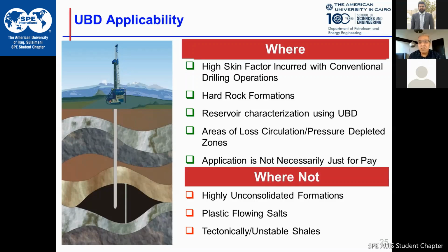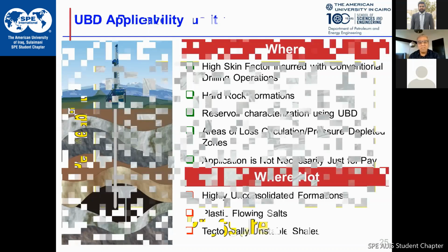Now, the other issue, if the clay content in shale is so high, let's say 40%, 50%, you have to take care of your base fluid, because if we use water, clay does swell with water. So you make a damage, intentional damage to the formation.